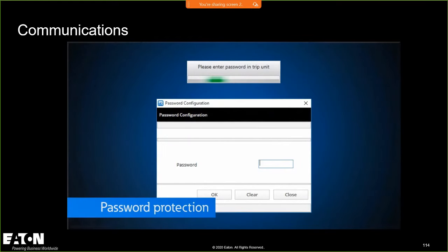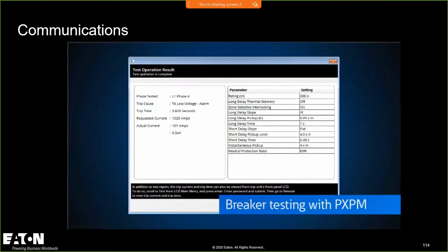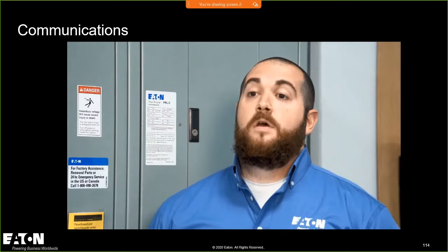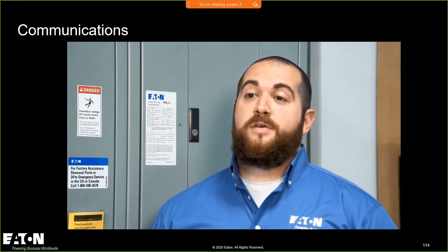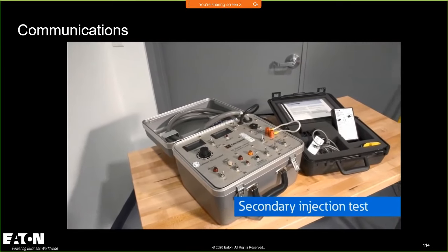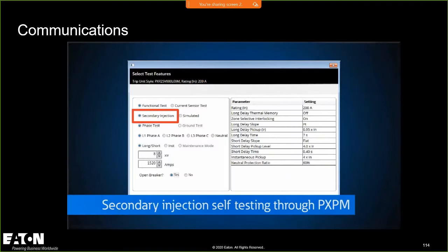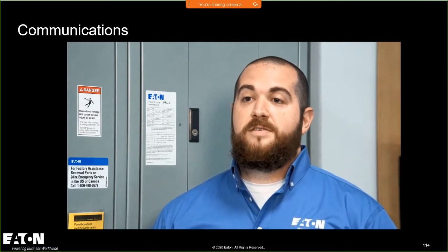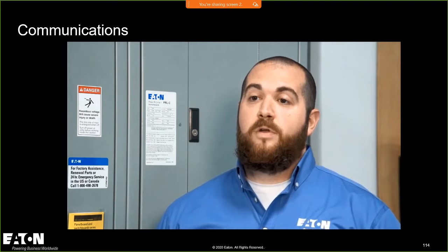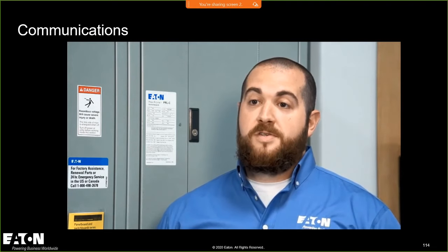Everything is secure and password protected, and now it even offers a new form of testing. In the past, our legacy products used a separate test kit to test the protection routines and trip actuator on the breaker. Now, with PXPM, you can actually do a secondary injection test with just your laptop, sending a signal into the breaker CTs to simulate an actual fault, and the breaker will respond just as it would if the